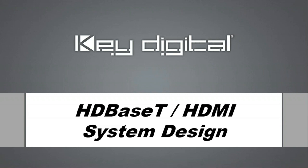problem is, HDCP. Now, as much as I love it, Apple TV seems to be a little picky when it comes to that. I know for a fact that I've got an HDCP system, everything's good. I've actually found out that sometimes with your HDMI cables, the Apple TV just says that, and by swapping a cable, it resolves that issue. You go and use that cable on other sources and have no issues whatsoever. So it's kind of a head scratcher, but these are the real world obstacles, and you know how to address them now.